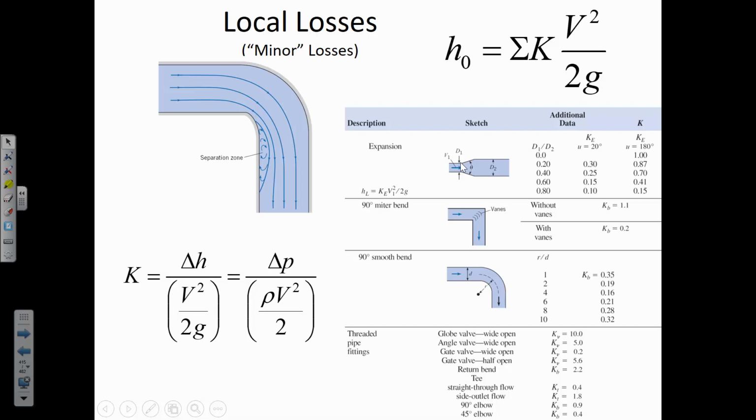And so this is what a 180-degree transition would look like: literally the water coming from one pipe is going to have to try and set up flow patterns into the other. And the reason there are losses is because of the turbulence and the rotational flow that occurs in those side pockets. And there's less of that in a more gradual transition like is illustrated here.